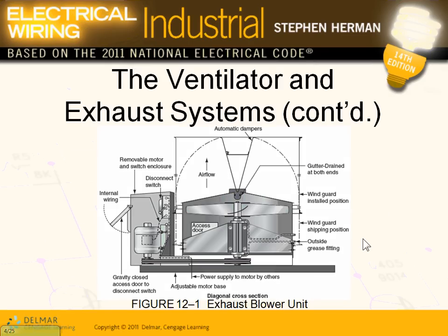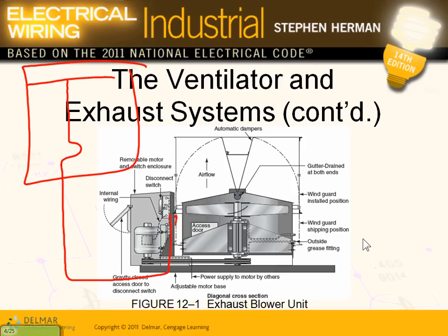Here's how your exhaust fans look. Chris, I will emphasize this area right here. So I can't remember where, I don't know. Let's just come from this area. Here's my disconnect right here, and I'm bringing it all the way to the overcurrent protection device inside this panel. So here's where my interface with this unit is. Bringing a feeder into the disconnect, which could be a fused or non-fused disconnect, and in turn feeding this blower or fan to feed the whole building, to feed the exhaust fan.